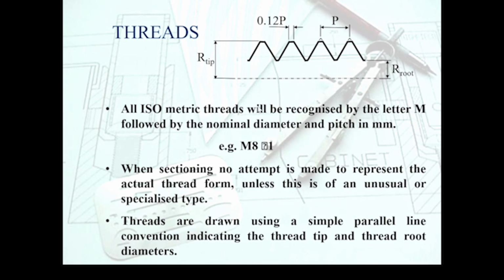Things will get a bit tricky whenever we have threaded shafts and threaded holes, and there are a few things you probably want to bear in mind whenever there is a situation like so. Okay, the threads are dependent on what thread type you're following. They can be anywhere from a trapezoidal form to a triangular to probably a square, which is not as popular.